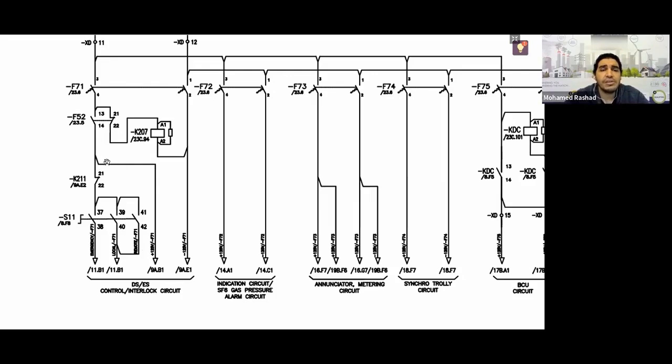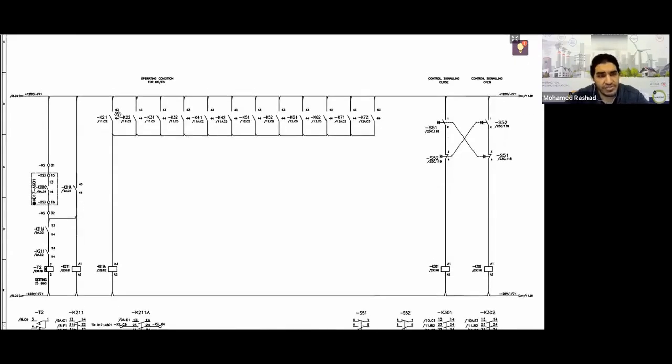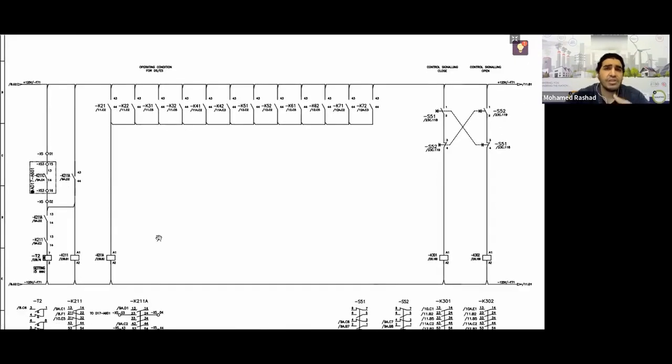First, if I disconnected the direct DC from the beginning here, I would have disconnected all the DC, which would cause several problems. The first problem is that this DC goes to page 9, which is this page, which actually contains the double operation activation, right or wrong. So the double operation was functioning because there was DC on this page. When you disconnect the DC from it, the double operation won't work. The long run time isn't working, right or wrong, right?